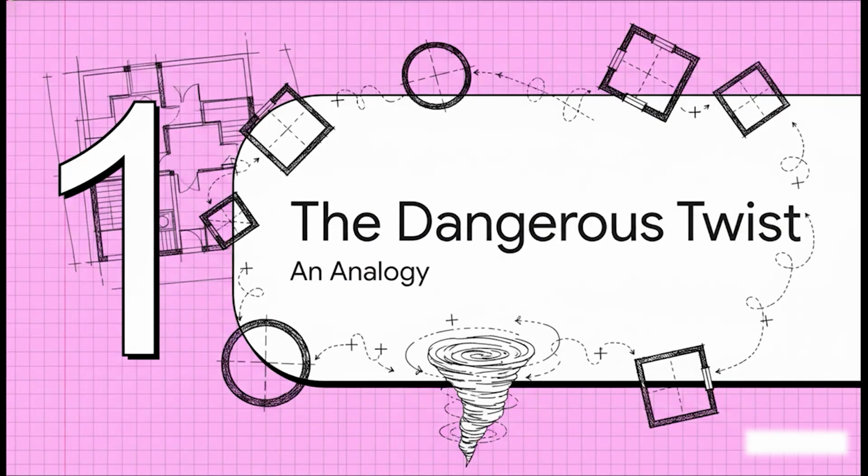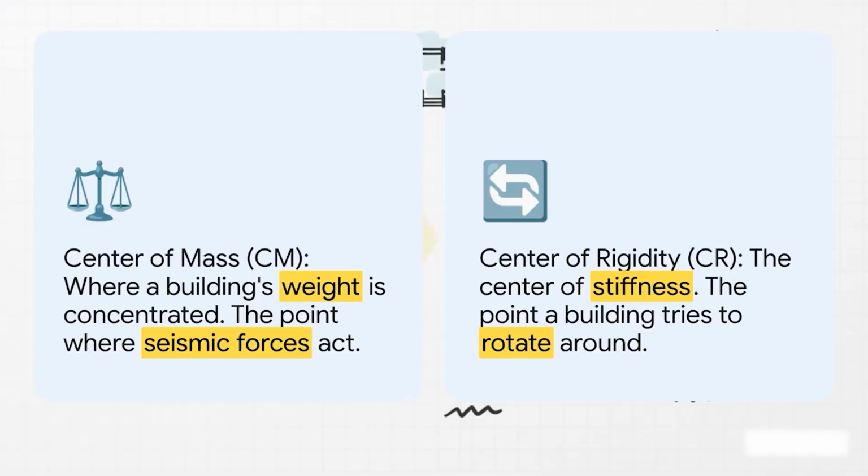To really get why a building would twist in the first place, you've got to understand this invisible tug-of-war that's happening inside the floor plan. It's a battle between 2 very important but invisible points. On one side, you've got the center of mass, or CM. Just think of it as the building's center of gravity. It's where all the weight is focused. And that's exactly where the earthquake's force is going to push.